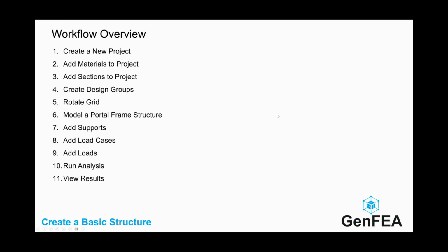The workflow includes creating a new project, adding materials and sections to the project, adding design groups to the project, working with rotated grids and planes, modeling the portal frame structure using the modeling tools and editing tools, adding analytical components such as supports, load cases, and loads, and finally running and viewing the analysis.